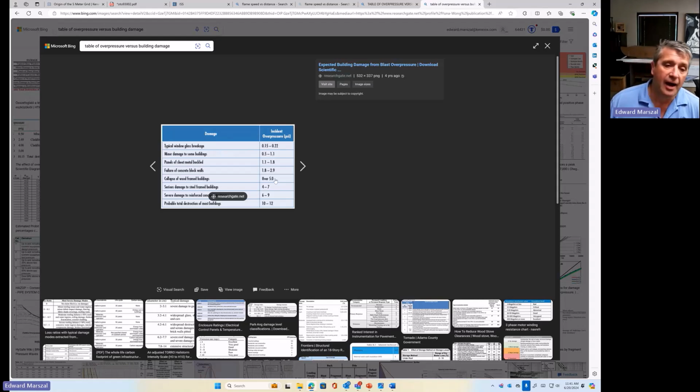Yeah. But if we at Connexus were asked to do this, what we would do, which granted is going to be on the high end of sophistication, we would run a leak rate model on the liquid leaking from something like, we would assume, a pump seal failure. What is the rate the material is going to leak? That is going to determine the evolution of a pool.